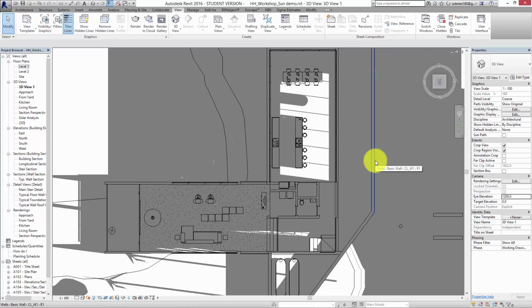Now, what I want to show you is a trick in Revit to make a simple sunshade, because if we start making sunshades, we start playing with families, and we start adding all this kind of stuff to it, we spend ages doing things. What we want to do is very quickly make a sunshade for the design process, apply it to the building, see how it affects the shading, and then modify it afterwards. So it's actually part of the design process, rather than you're just playing with 3D modeling.